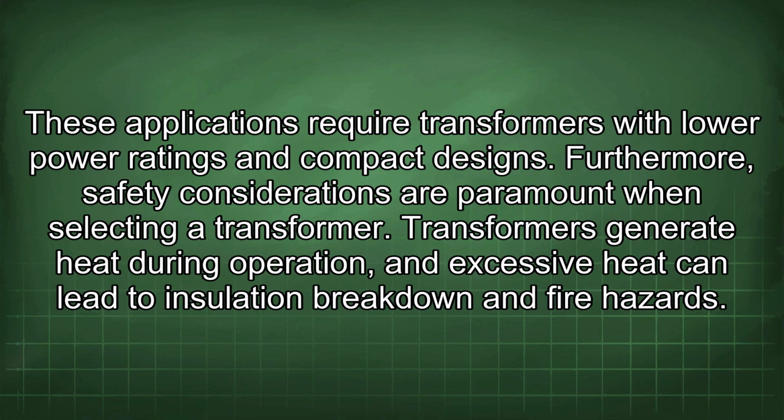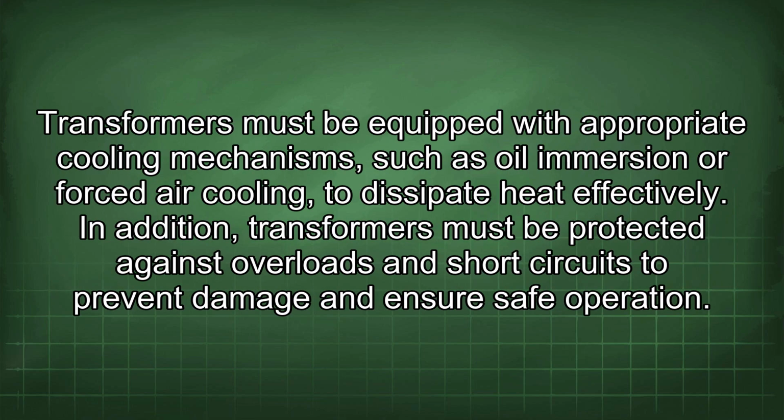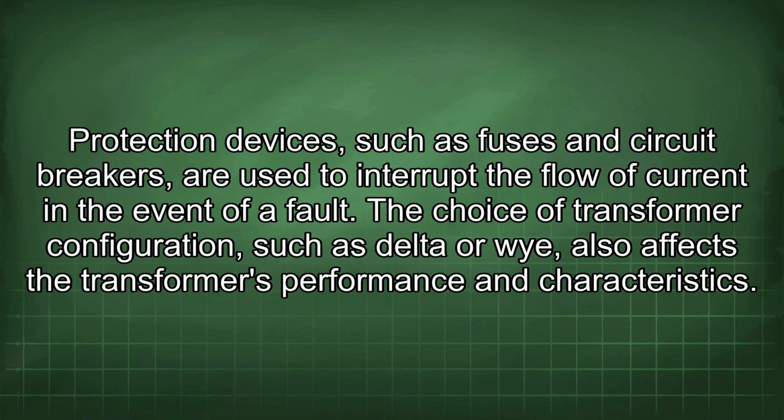Furthermore, safety considerations are paramount when selecting a transformer. Transformers generate heat during operation, and excessive heat can lead to insulation breakdown and fire hazards. Transformers must be equipped with appropriate cooling mechanisms such as oil immersion or forced air cooling to dissipate heat effectively. In addition, transformers must be protected against overloads and short circuits to prevent damage and ensure safe operation. Protection devices, such as fuses and circuit breakers, are used to interrupt the flow of current in the event of a fault.